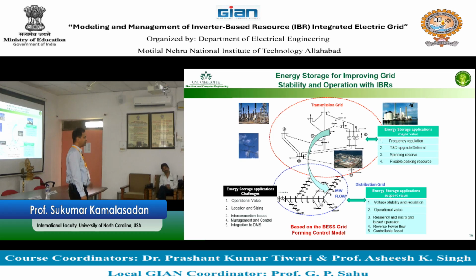So you consider that in many of our models, especially on the electric grid side, I don't consider myself an expert in power electronics, but on the electric grid side we always say that switch losses are negligible. These are the kind of things which you do, and then you model it. But much of it is not going to the switches, by the way. It is all going to these big filters that are probably sitting there. The inductors, basically, especially on the AC side.